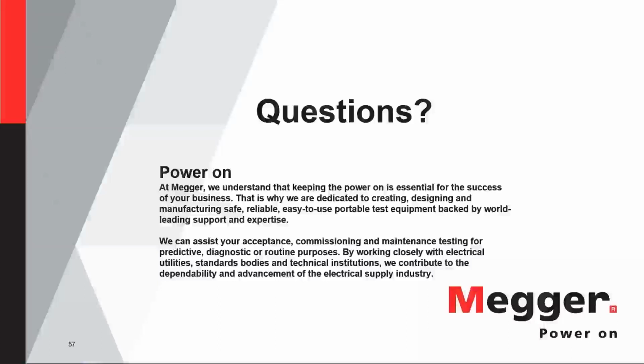The Megger OTD is also for oil testing, but if you remember from the very first few slides, when I discussed electrical testing on oil, the dissipation factor and resistivity are also called for in the standard. The Megger OTD, the Megger oil tan delta, will help you do both power factor and resistivity measurements in oil.